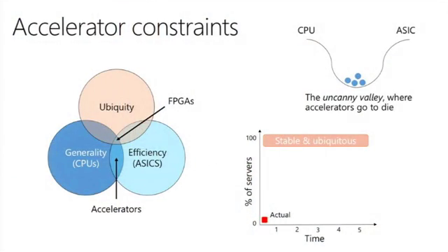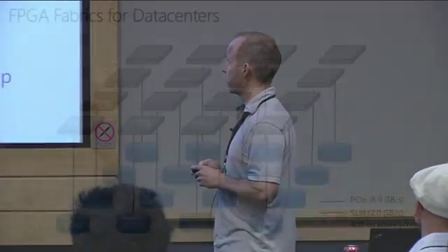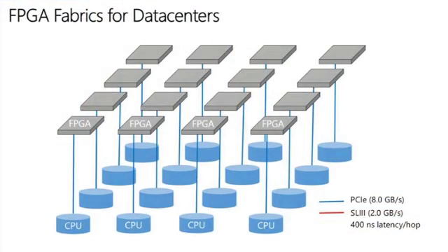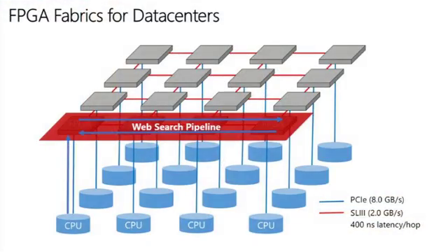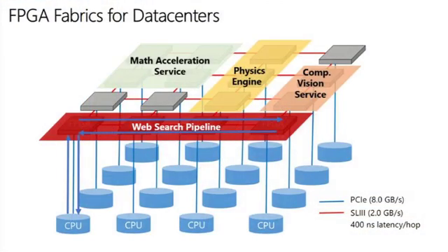And so in the cloud, we've made a very big bet, as a lot of you know, on FPGAs to try to bridge that gap. But that doesn't really work for the mobile space. Some phones have had very small FPGAs in them, but since FPGAs use spatial parallelism, you tend to need a lot of silicon real estate to do interesting workloads, and that high silicon real estate is too expensive for these small mobile devices. Okay, so in the data center, we dealt with this by building this fabric where you can offload services, and you've probably heard some about that in this faculty summit. But this doesn't really solve the problem in the mobile space.